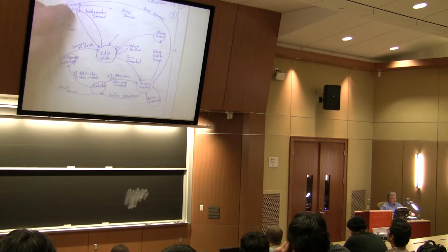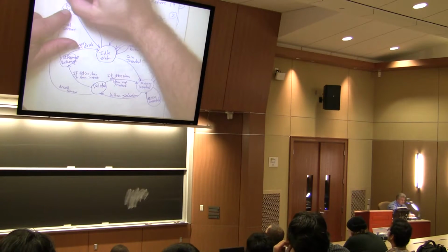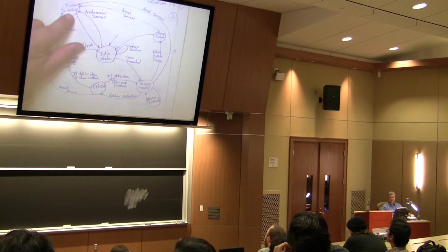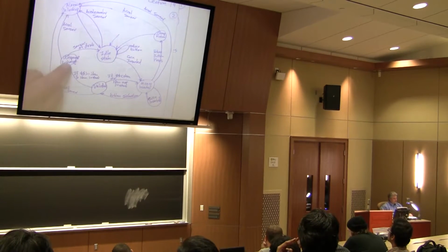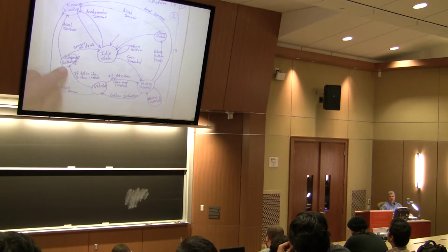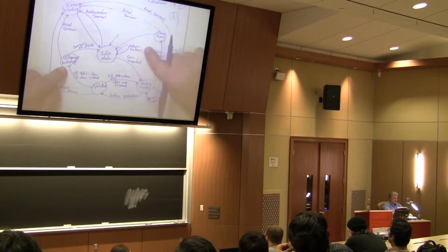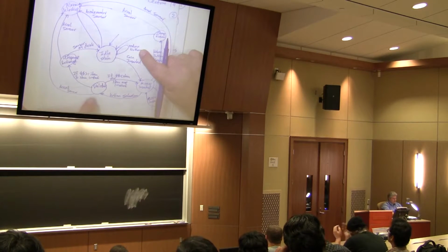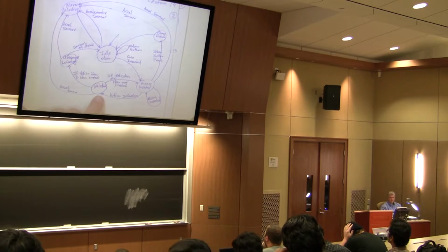Because what if you're in the change return state, or what if you're in the alarm and lockup and somebody presses the return button? Just ignore it, right? What if you're in the dispense and issue change state and somebody presses the return button? You want to ignore that, right? What if you're in the validate state?